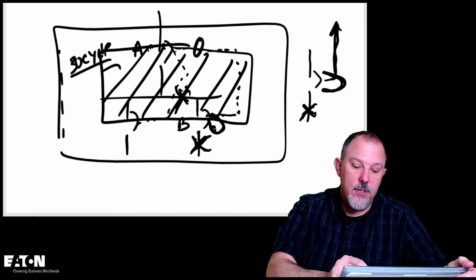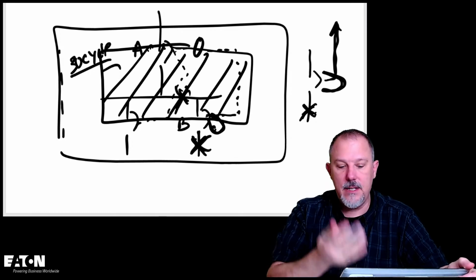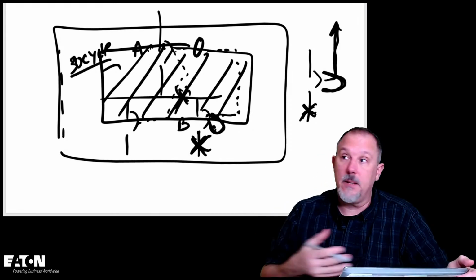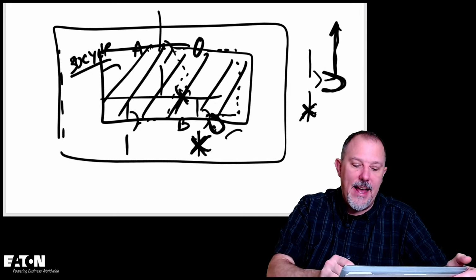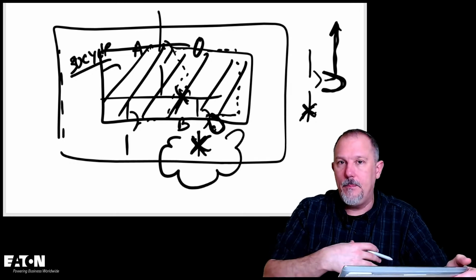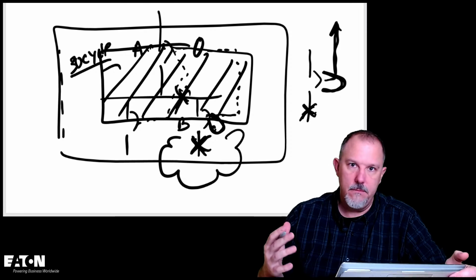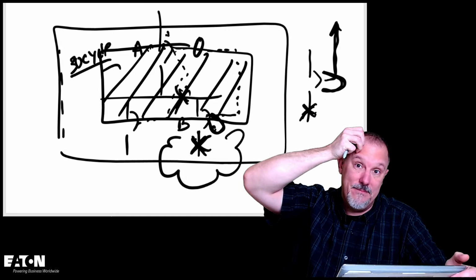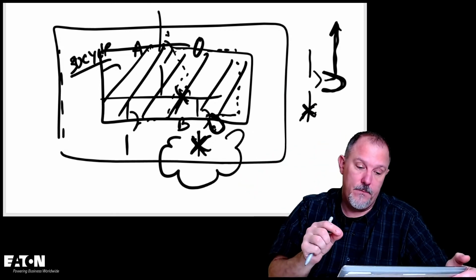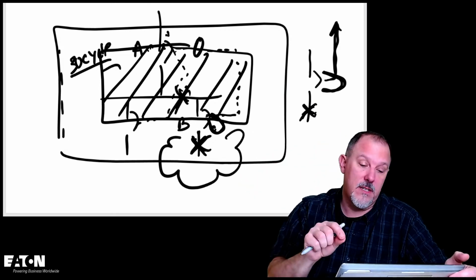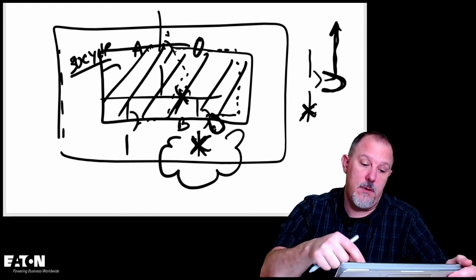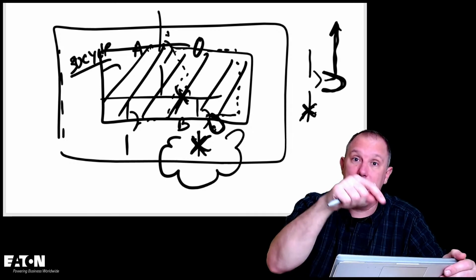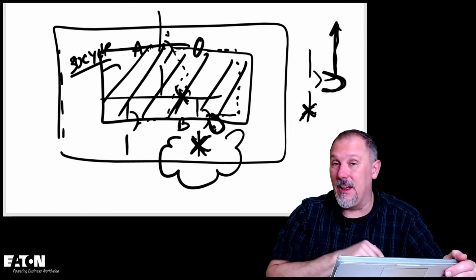If I have a fault downstream of the downstream device, and let's say it has a 3-cycle delay, or a 30-cycle delay, or a 12-cycle delay, it's a big power breaker, I could have a plasma cloud that could possibly cause a line-side propagation. So technically, and I've seen people go either way on this, some people will say I'm going to label it based upon the incident energy, the clearing time of the zone selectively interlocked systems.